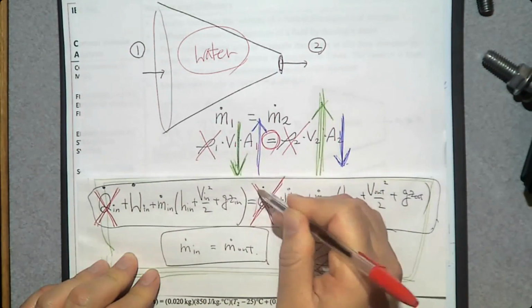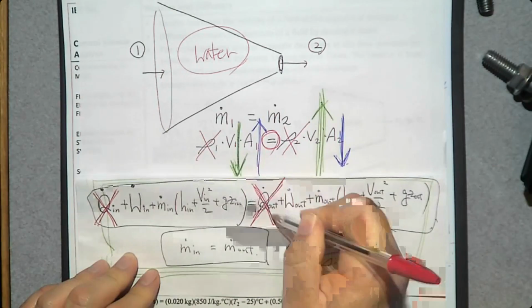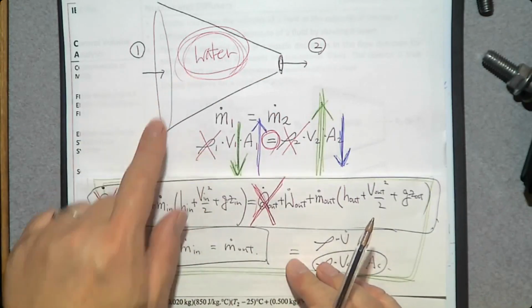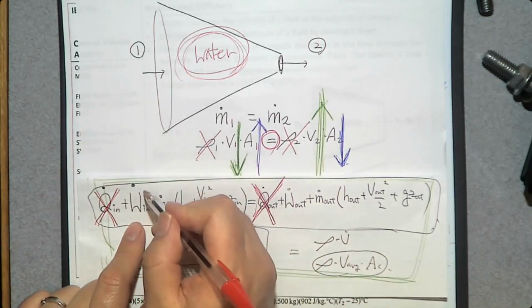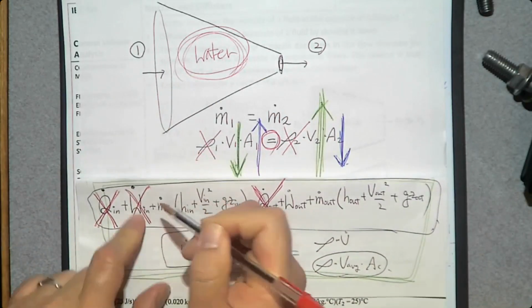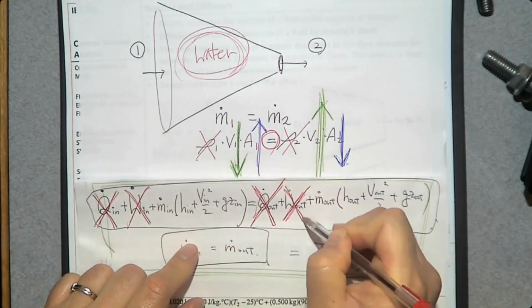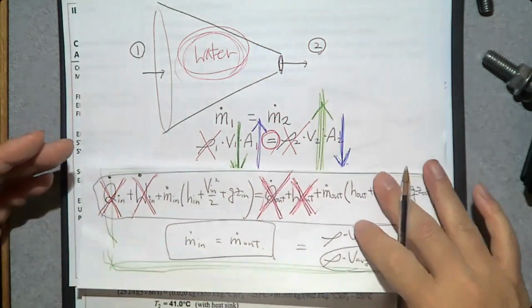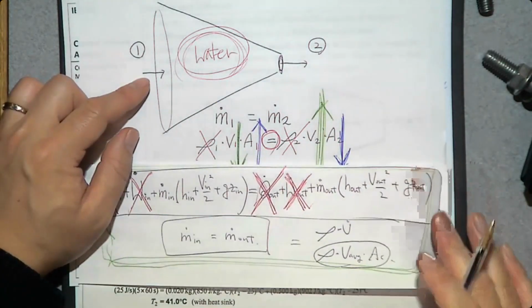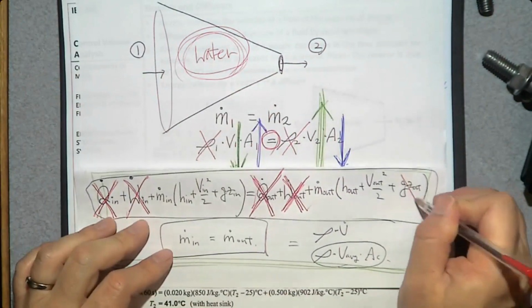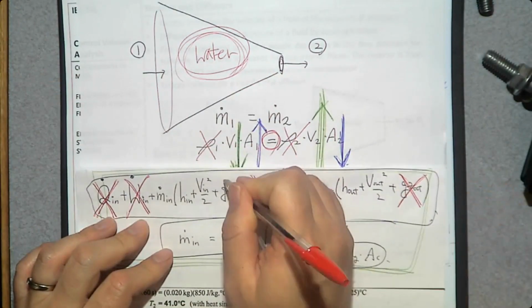Usually no, unless the working fluid is at extremely high temperature. Does the nozzle consume any electricity, any work? No. Does the nozzle produce any work, like electricity? No. Is there a potential energy change? At the inlet it is on the ground, at the exit it is on top of Mount Everest? No. The potential energy change is negligible.